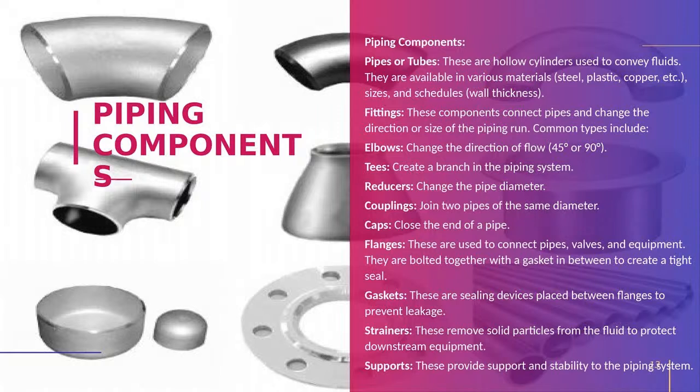Flanges are used to connect the pipes with other components, like pumps or compressors, which require maintenance. Pumps we have to take out for maintenance, so we cannot weld the pump nozzle with the pipes. So we need a flange joint wherever maintenance is required, wherever we expect a choke in the pipelines,